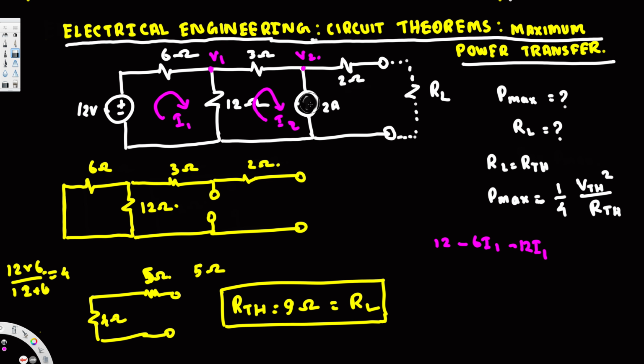So if I take current in this direction, everything will be easier. Okay, I take the mesh current in this direction, I2. So from this one we know that I2 is already there, because in this one this is the only current going through this. So I2 is going to be equal to 2 ampere, and let's solve the mesh 2 circuit. Okay, this is equal to 12 I1, and this is going along this direction.